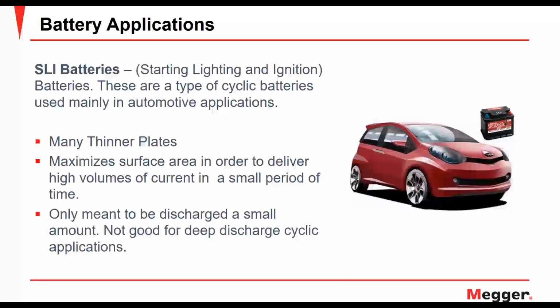And one note here is that if, for example, your battery died in your car, it's better to jumper it and then replace it in a shorter period of time, rather than just keeping it for a longer time, because once this battery gets discharged, it will lose its life pretty drastically, since they are not designed for this application.